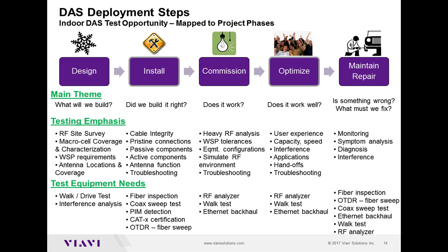For example, if you have 4 different bands, you may have an AWS, PCS, a 700 LTE, or all those different 4 bands working together. Let's say I'm just giving an example from a North American standard point of view, right? So in that scenario, you will do a good baseline. You want to also see how strong the signal from outside is coming, especially in the cases when we were talking about a DAS built for capacity. You may have coverage, but you do not want the macro cell to be taking over when there is a DAS deployed later on.